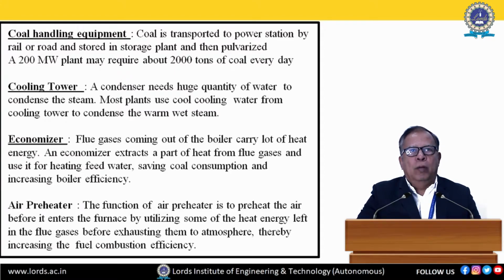Then economizer. The flue gases coming out of the boiler carry a lot of heat energy. So the economizer extracts a part of the heat from flue gases and uses it for heating feed water. By doing that, it saves coal consumption and it increases boiler efficiency also.